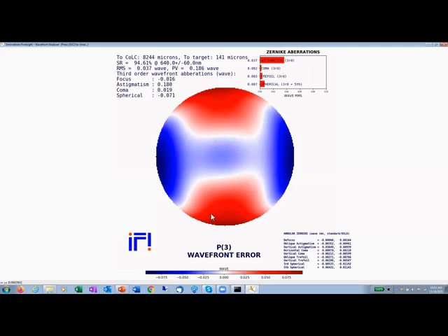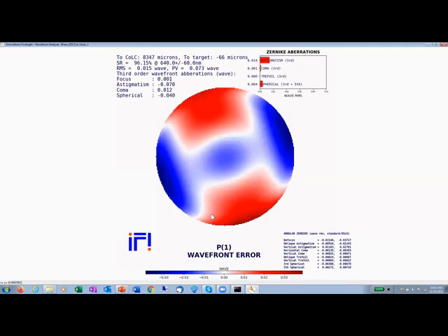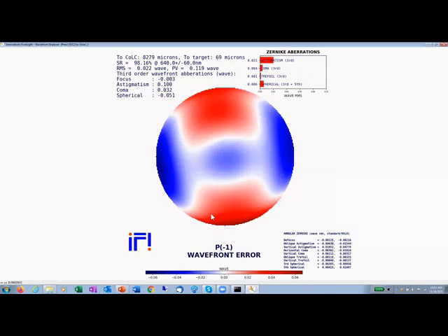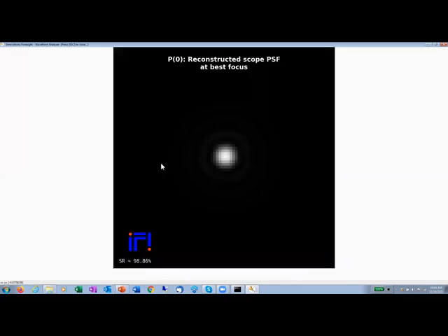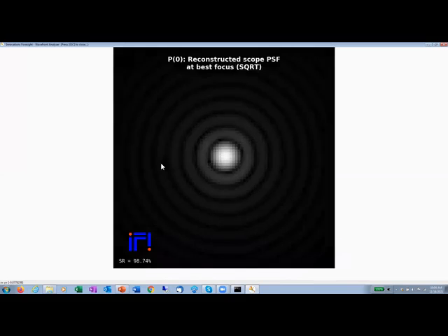So if I go down and do the same thing with the pinholes below the optical center, below pinhole 0 on axis, and I go to, let's say, -3, you see I have pretty much the same level of astigmatism at -3, which is expected since it's a symmetrical system with this achromat. Okay, let's go back to pinhole 0. We can see from pinhole 0 the PSF, which is pretty good. Take the square root of it, you get a better idea of the diffraction rings. And you see it's perfect. Of course, the Strehl ratio is almost 99.